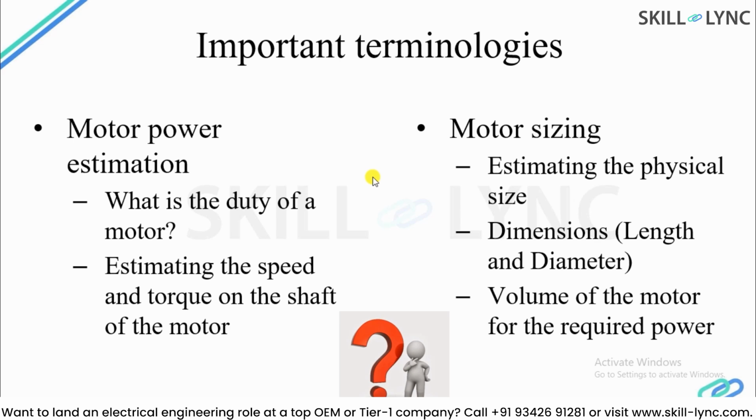And fundamentally motor sizing is nothing but how the required power is actually going to be kept inside the available volume of a motor. So motor sizing is the exercise which deals with determining how much volume the motor will require, or for a given volume how much power the motor will be able to produce.